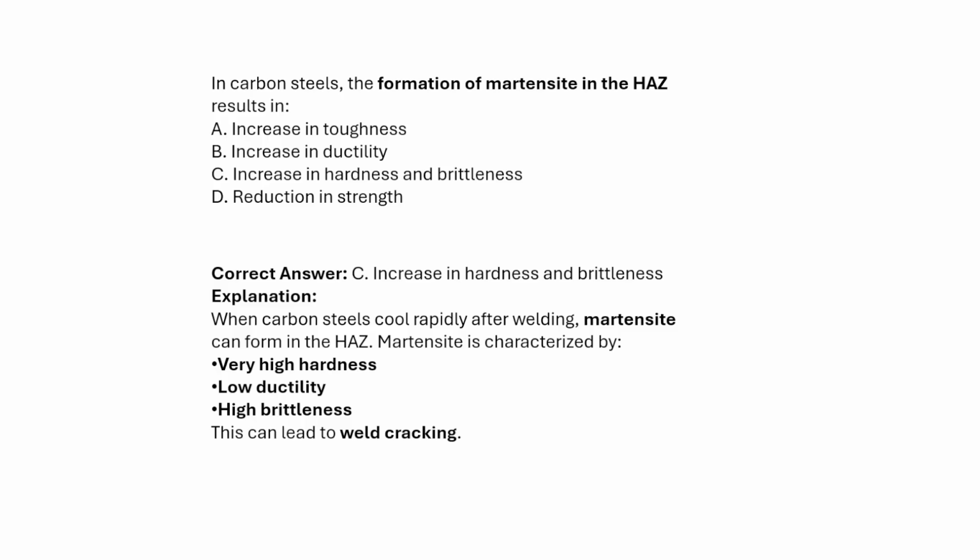From there, if it cools very fast, it avoids the nose of the curve and reaches the martensitic phase. The proportion of martensite depends on the cooling rate. If we cool very fast, it will contain 100% martensite. If we cool moderately, the percentages vary between pearlite and martensite.